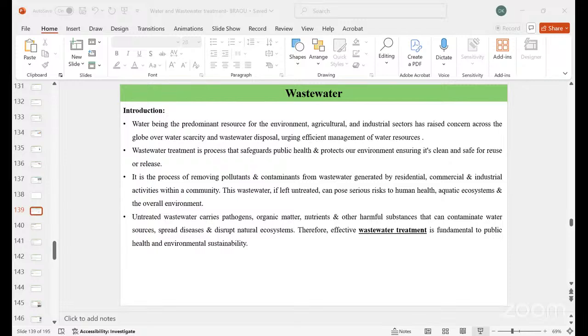So, coming to the key operation, the key design and the operational phases: the tank geometry can be either rectangular or circular. Inclined plate settlers, that is lamella clarifiers, significantly increase the settling efficiency by providing a series of inclined plates. This also requires a footprint of the tank, and the plates require a large surface area for solids to settle down at the bottom.